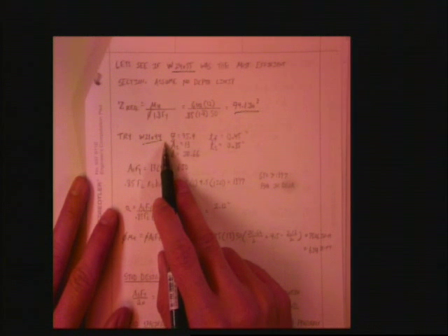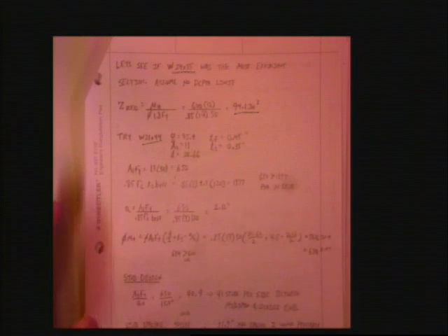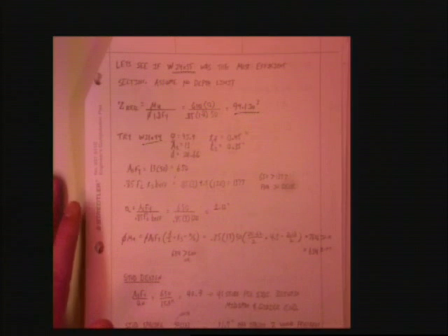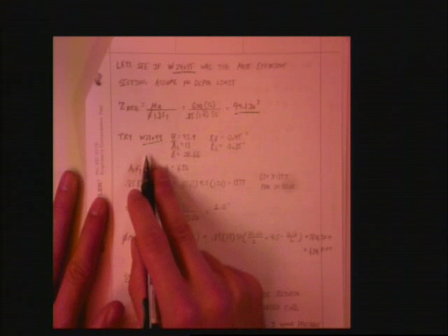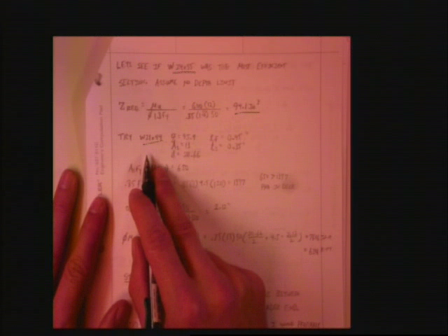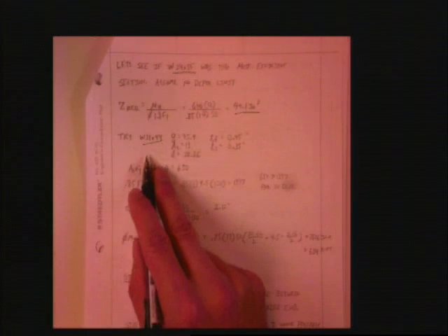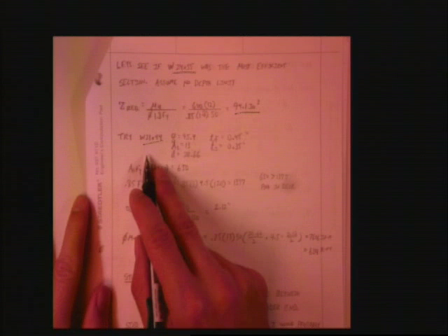Also, if we have a continuous girder, which we didn't, where you could have negative moments, then yeah, you better be careful. You may end up using case 2 or case 3 of those C sub B calculations that we talked about in the past to work the problem. This is a perfect way. I mean, we think of the deck as bracing the top flange, right? And the bottom flange is only braced in a certain couple locations. But right now, we'll go ahead and assume that there is no L sub B.